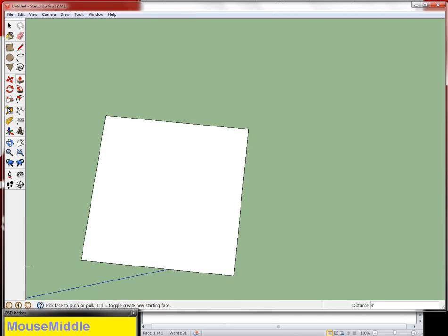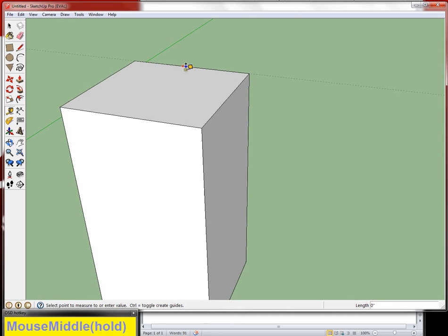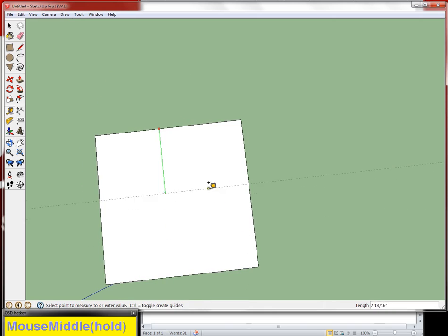I'm going to make this a very consistent 2 inches. So when I pull, I'm going to grab the tape measure tool, and then I'm going to click on this back line and pull down, or rather pull across the top of the shape. It depends on where I'm looking, whether or not I'm pulling over or pulling down with my mouse. But I'm going to pull it this way.